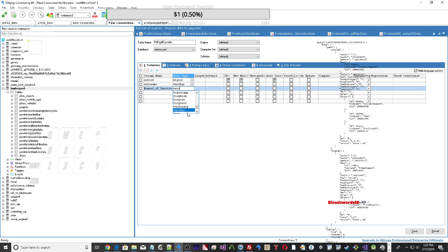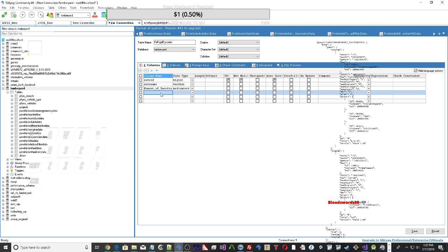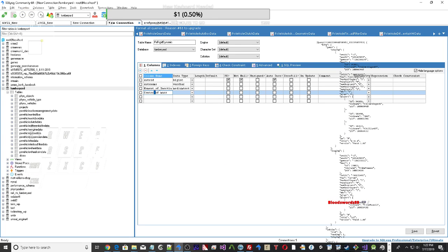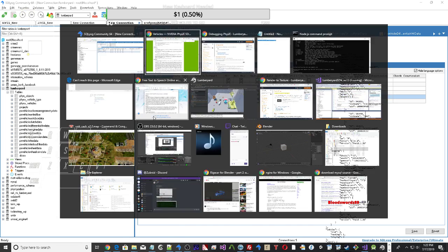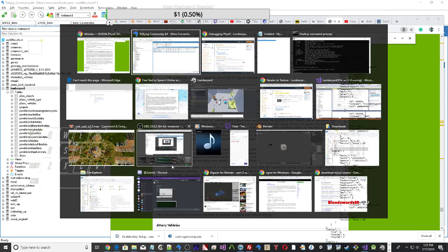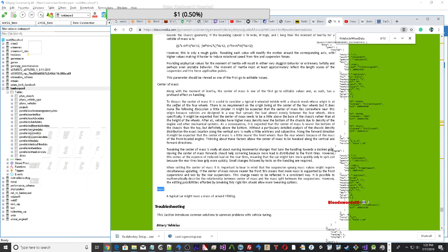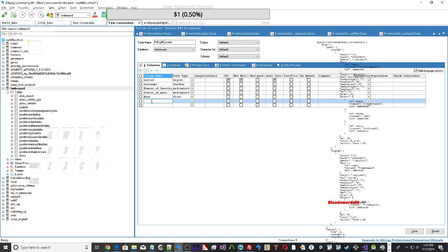The code above first instantiates a PxVehicleWheelsSimData instance with internal buffers that are large enough to store configuration data for 4 wheels. This configuration data includes fields such as suspension strength and damping rate, wheel mass, tire stiffness and suspension travel direction. The next step is to create a PxVehicleDriveSimData4W instance. This structure stores the configuration of the drive model and includes data fields such as engine peak torque, clutch strength, gearing ratios, and Ackermann steering correction.